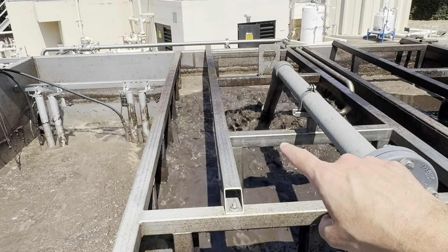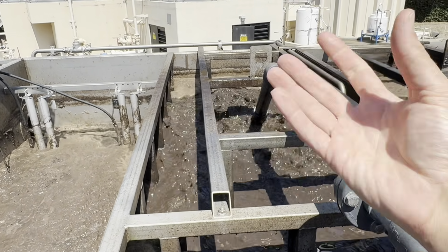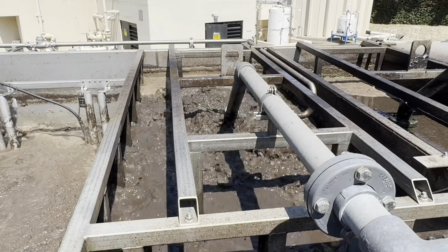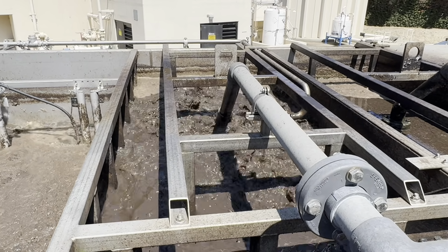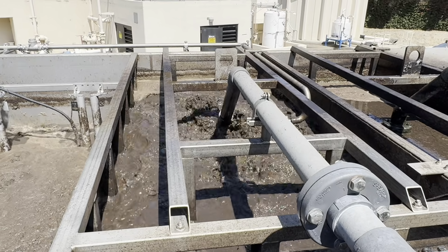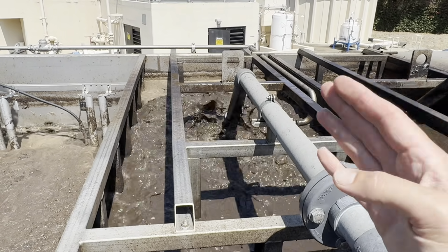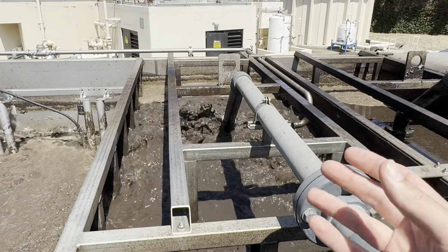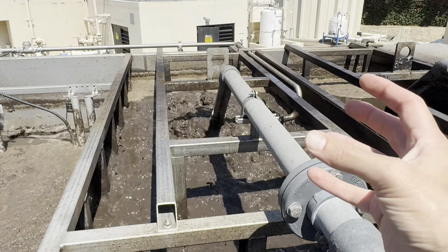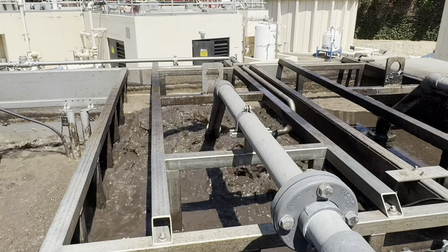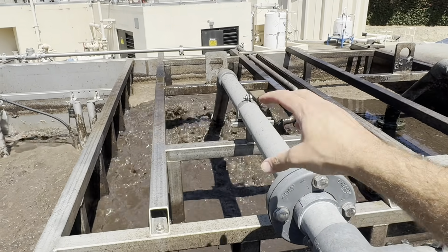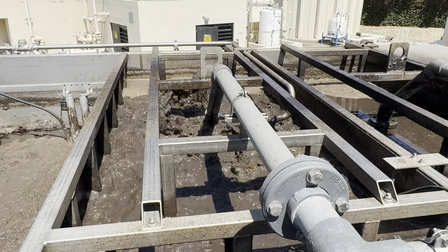So what's happening here with this blower that's constantly shaking up these membranes is we've got the spaghetti noodle style membranes, and so these are Suez, which I think actually Veolia just bought out recently. But anyway, this air scour knocks them around and makes sure that they don't blind due to the biology sticking to them, because there's a vacuum being pulled by the permeate pumps to pull, this is the permeate line right here, to pull that clean water out of there.